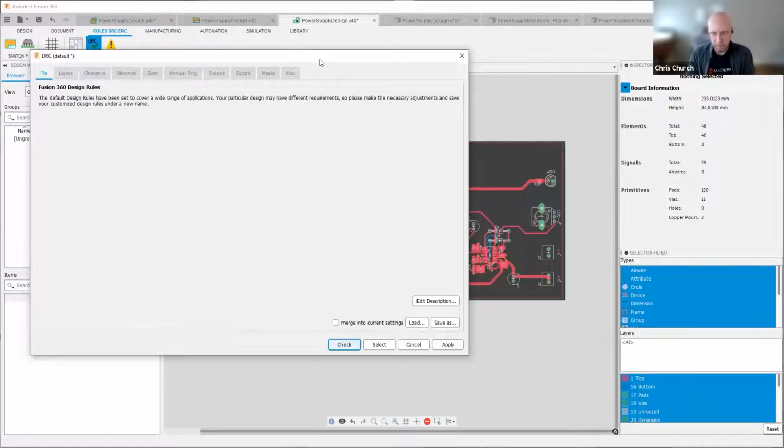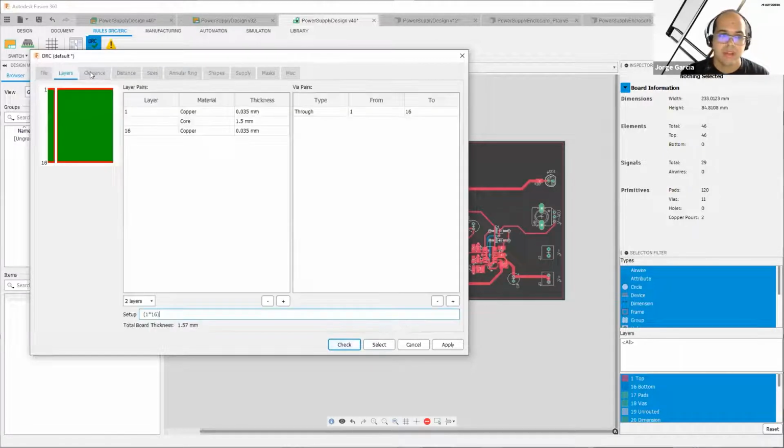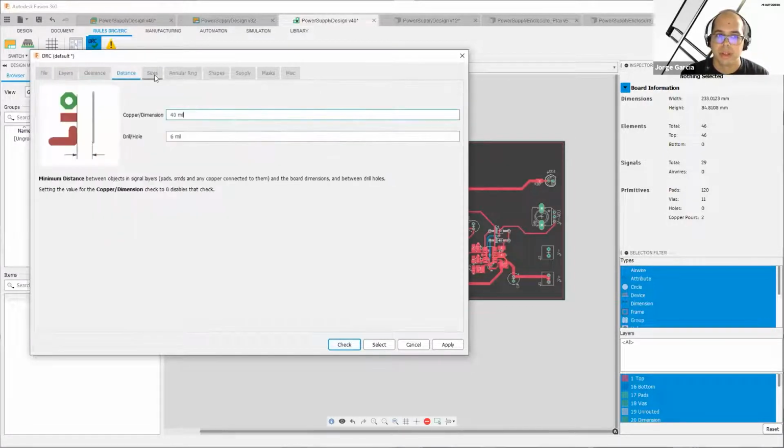And this is something we ask everyone start with. And at MacroFab, we try to make that as easy as possible by giving you the rule files. You don't have to read a web page and type in all the values. Our focus is really making your life as easy as possible. Awesome. So that's something to keep in mind. That's a benefit that users will obtain by going to MacroFab, because you just give them the file. If you're dealing with a manufacturer who doesn't have a DRU file already made, then you have to look up their specifications on their website, interpret them, and then fill out the corresponding fields here in the DRC.